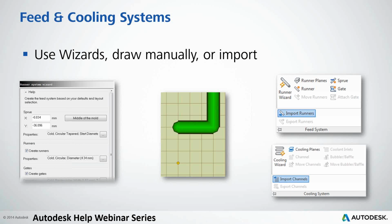With regards to the feed and cool system, you can use wizards, draw it manually, or import the components. Whenever you use the wizard, you just go in and specify what kind of runner you want, what kind of gate you want. You can also specify the position of the sprue. After that, you just click apply and it will automatically draw that runner system for you on the part or parts that you have.